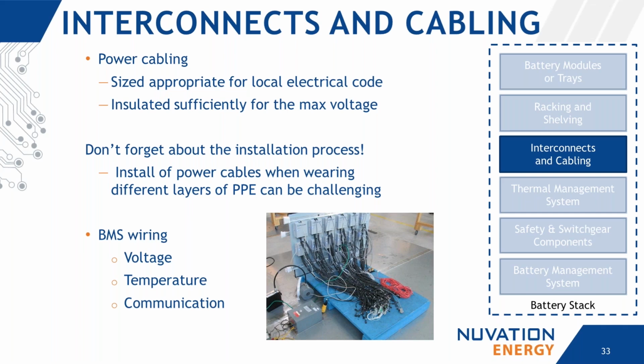Then with BMS wiring, there are three categories: the voltage, temperature, and communication cables, as we've mentioned. There could be a lot of BMS wiring, so detailed planning around the routing and lengths can lead to a huge installation effort savings.